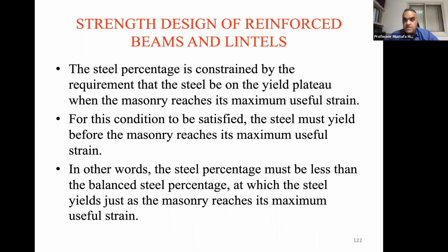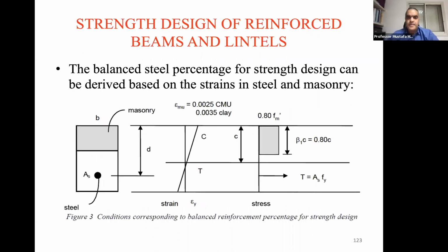Reinforcement limits, minimum and maximum, like we have in concrete. For now in ASD we don't have that. In strength design we have that, and that's very important for the behavior of the beam. Think of concrete. Why do we need the minimum reinforcement ratio, and why do we need the maximum reinforcement ratio? Of course, that affects the behavior of the member. What will crack first, what will yield. Is it over reinforced? Is it under reinforced? Is it ductile? Is it brittle? So this is very important and has been developed and incorporated into the strength design.